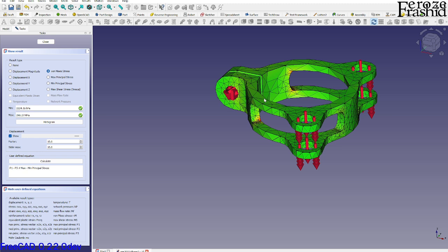So it will not break because the rupture ultimate stress is higher than that. Ultimate stress is like 400 MPa. So it will probably stay, but it will start yielding. So you will see the deformation towards failure after 1000 Newton load.